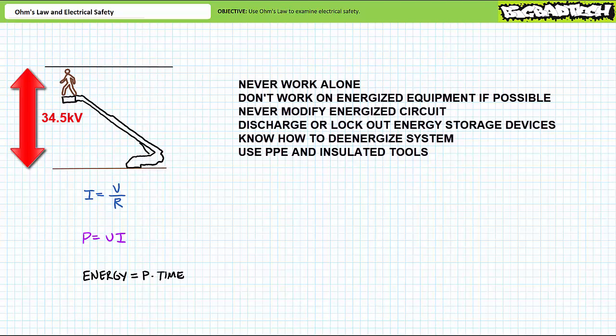Use personal protective equipment, including safety glasses. Remove conductive jewelry like rings, and if you got long hair, tie it up out of the way. Never, ever wear a tie or a scarf around rotating mechanical equipment. Matter of fact, never wear a tie ever. Insulate your body. Use tools with insulated handles, and don't become part of a conductive path. If at all possible, work one-handed and maintain clearance by not leaning on other parts of the equipment. This ensures a conductive bridge isn't formed through your body.